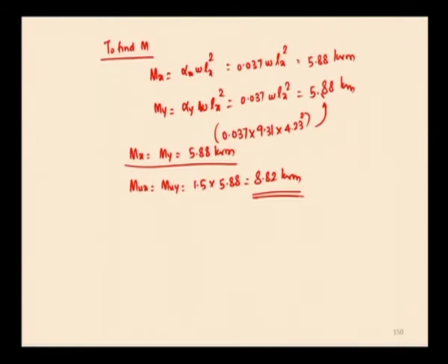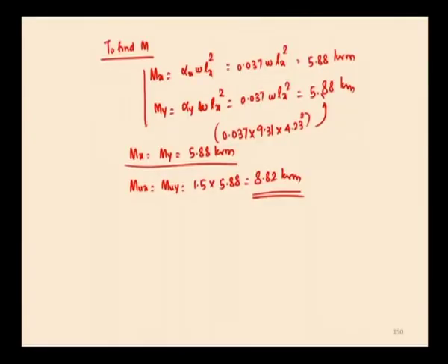So, this is the way of calculating the bending moment coefficients for a two-way restraint slab, which is having adequate provision to resist torsion at the corners. So, here the condition of slab is one long edge discontinuous, other 3 edges are continuous. That is why it has both negative as well as positive moment along both the directions. They have given bending moment coefficients along x as well as along y direction for both negative and positive signs. So, here Mx and My we have calculated.